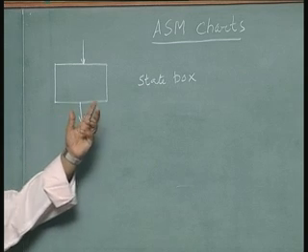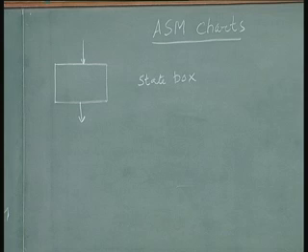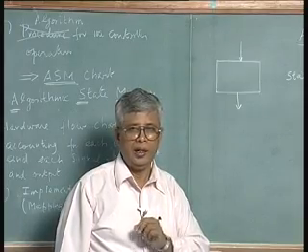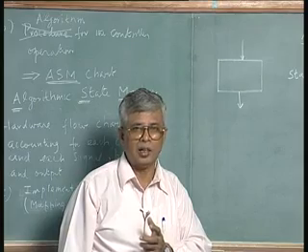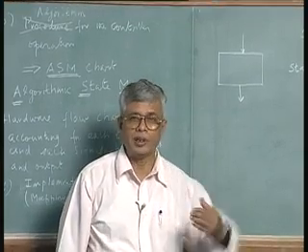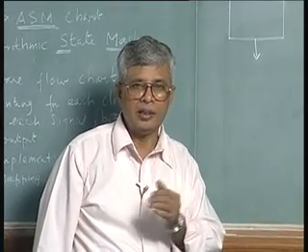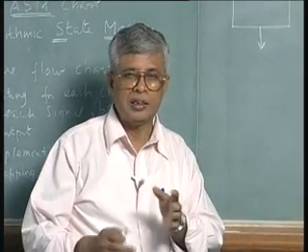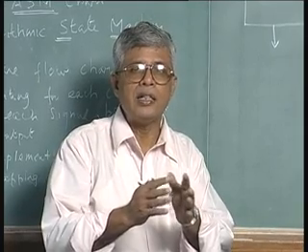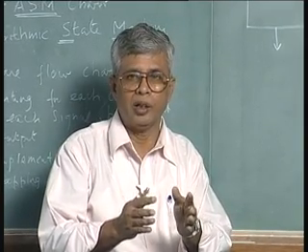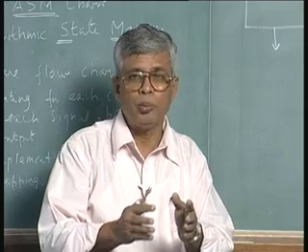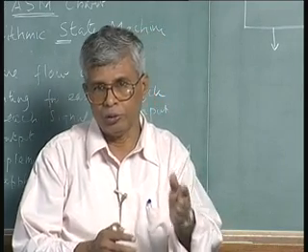This represents the state, as we understand, because in a state graph you know that at each clock cycle the circuit or the system resides in a particular state, and in the next clock cycle the circuit or the system can change to another state or continue to remain in the same state. But you define a state, in a state graph or in a digital system, as the period for which the circuit will not change, nothing will change in terms of its behavior, in terms of the input output. In terms of the output, of course; input you can always change, but then it is better to synchronize it.